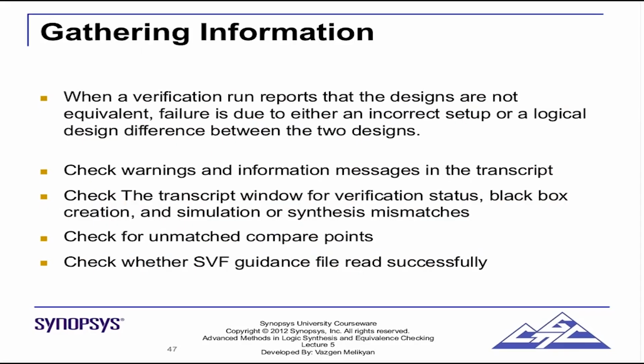When a verification reports that the design is not equivalent, the failure can be due to an incorrect setup also, like the clock gating part I told you. In case you have not done anything special for clock gating, Formality will report a number of latches as being extra, not matched, plus all the flops that are affected by clock gating, it will report as not equivalent. This does not mean that the design is not equivalent. This means that there is some problem in setup, or you can even have a genuine logical difference.